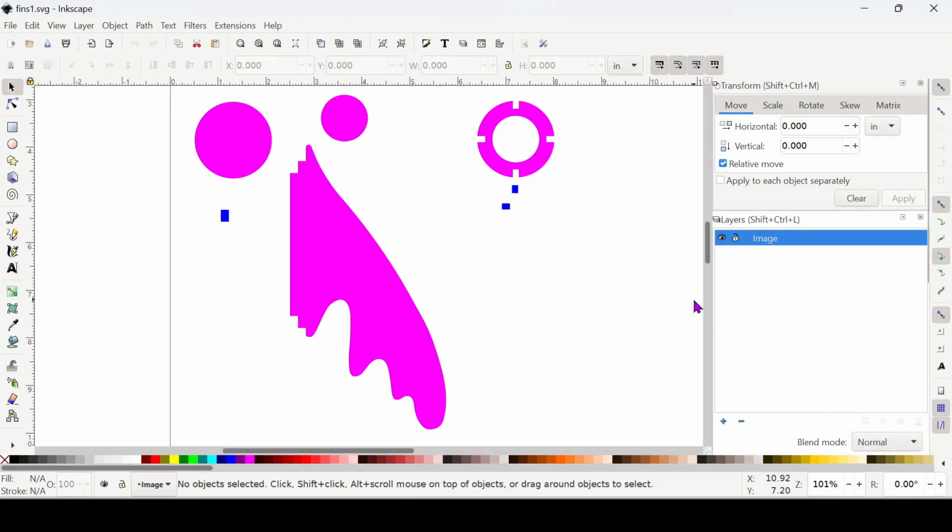Since we wanted a stylistic edge on the fin here, we did do the freeform. We drew it in Procreate and then brought it over here into Inkscape to add the geometries to make the actual fin can with the centering rings. We didn't do any parametric modeling of this because it was all relatively straightforward. To get that imported into OpenRocket, you have to save it as a PNG with the root edge on the bottom and the fin in black on a white background. Now with our trailing edge looking like dripping goo, we're ready to send this off to the laser cutter.